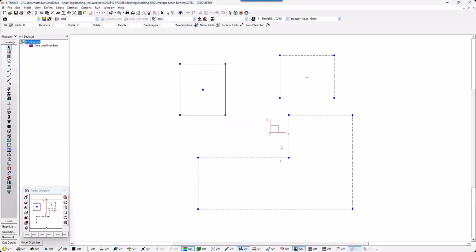Maybe just as an illustration, if I reselect these and turn this off. Actually, let me revise that. I turned this mesh selected panels and seed nodes only option off. I'm going to unselect these again, just like I did before, with the only difference being that now I have this toggle turned off. And now I can go into mesh panel elements and type membrane plate or shell once again.